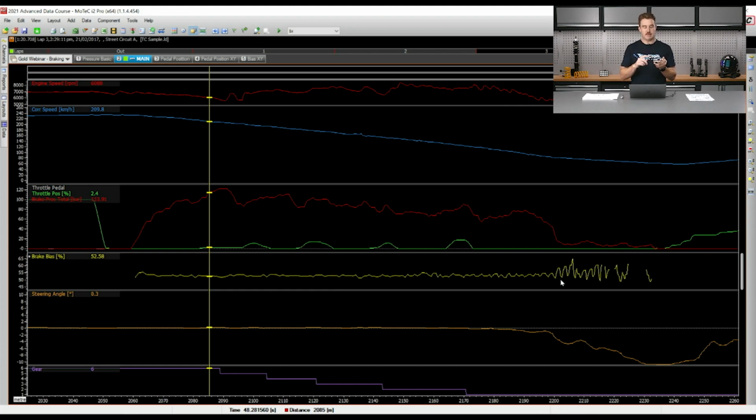So it can be any of the connections, any of those bearings or bushes causing that problem. It can also be different amounts of stiction you get within the bores of the master cylinders themselves. It'll just depend on your exact system where those bias variations are coming in.